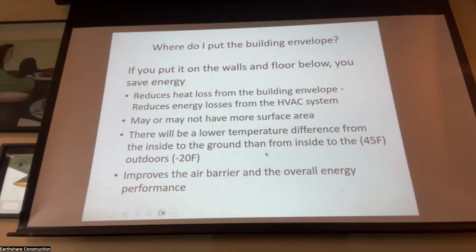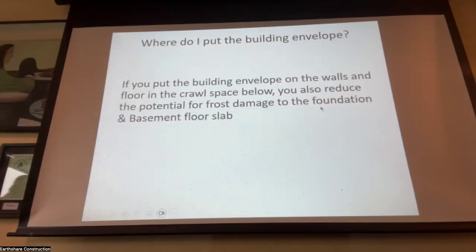And doing a complete air barrier underground is a little easier in a lot of cases than doing it above grade. And this is just a comment again, you can keep the foundation warm, you have less likelihood of frost action, where you'll have heaves in the slab or in the wall.